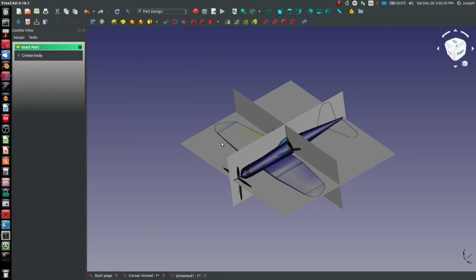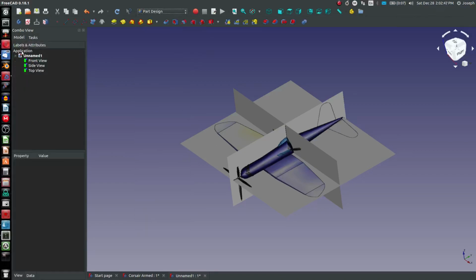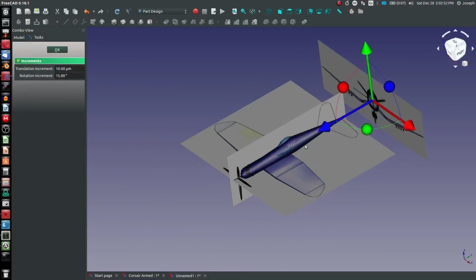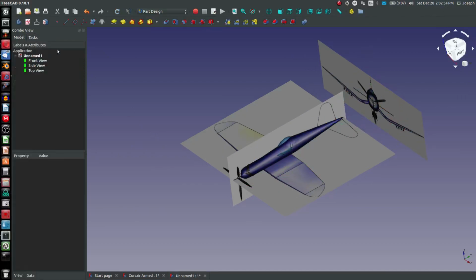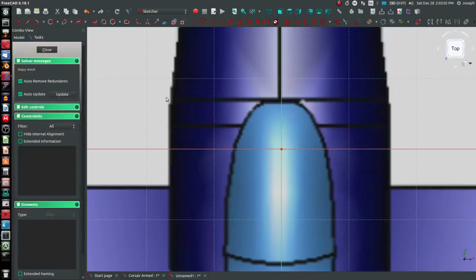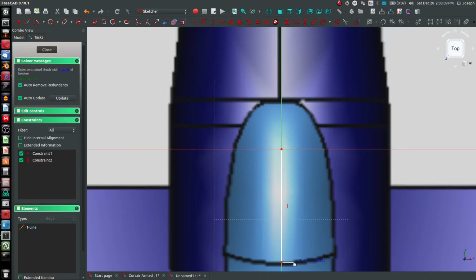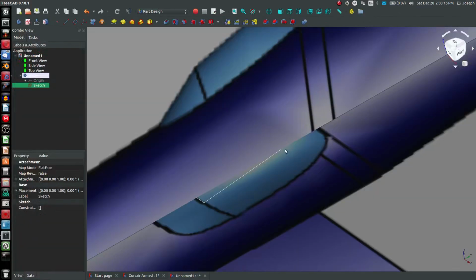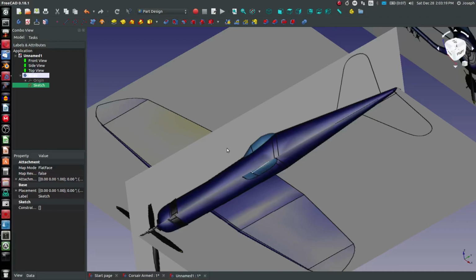We'll go down to part design, and from the tree I can double click and position my front view anywhere. So what would be easiest is to make a sketch in part design that calls out where a part is. I'm going to choose the XY plane. I need to call out where the origin is, really. So I'll choose Polyline, select the origin, and make a little arrow that indicates where my origin is, closed. So now I can see where my origin is in this sketching environment.